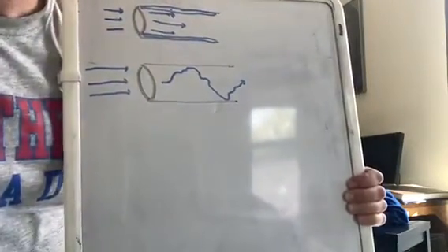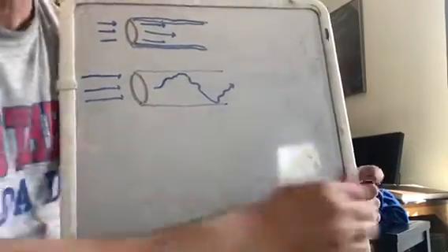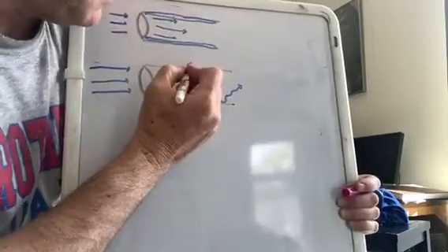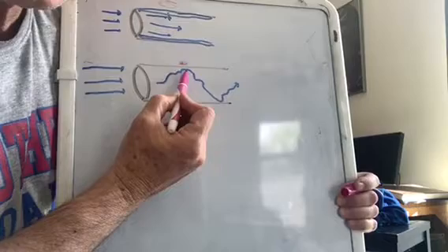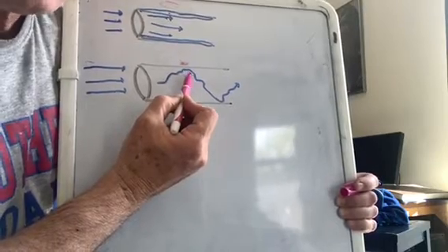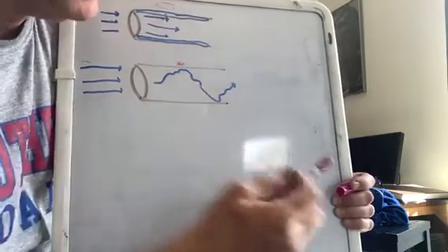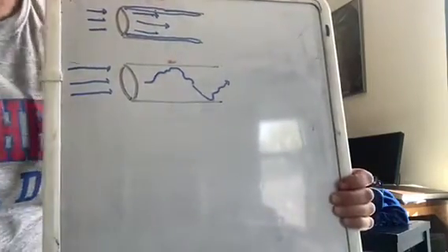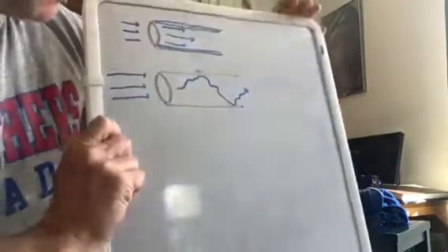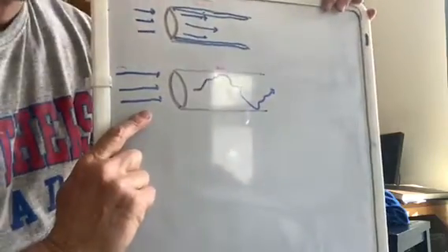Well, how is that for heat transfer? And the answer is it's just great. Okay, if this top of the pipe is warm, when this water comes up here and touches that pipe, it picks up the heat and brings it and deposits it in the middle. So with swirling flow, we get much, much better heat transfer. And as a consequence, just by increasing the flow rate, we can get turbulent flow.